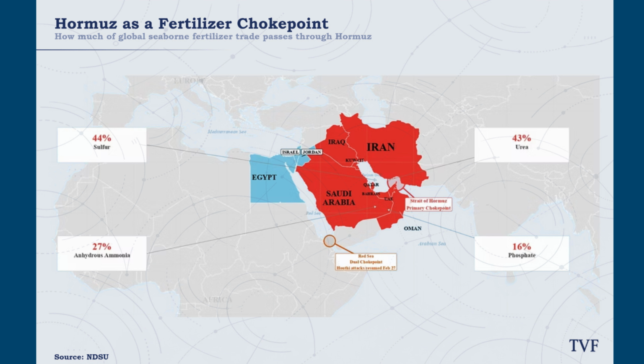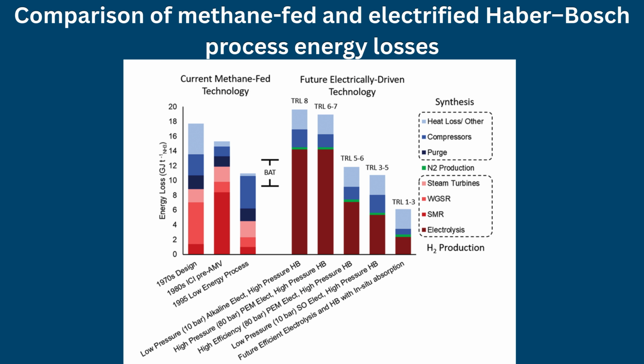This approach decouples ammonia synthesis from fossil fuels and can substantially reduce life cycle emissions. For example, replacing SMR-derived hydrogen with electrolytic hydrogen can reduce CO2 emissions per ton of ammonia by more than 70%, depending on the carbon intensity of the supply. Moreover, the electrification of compressors and auxiliary systems further enhances overall energy efficiency by eliminating losses associated with steam-driven machinery.